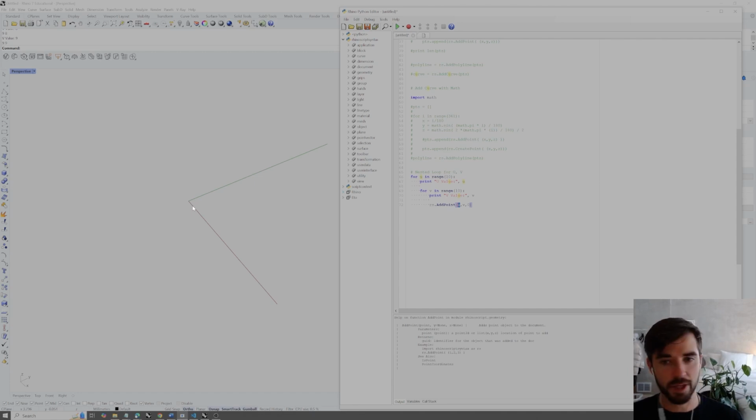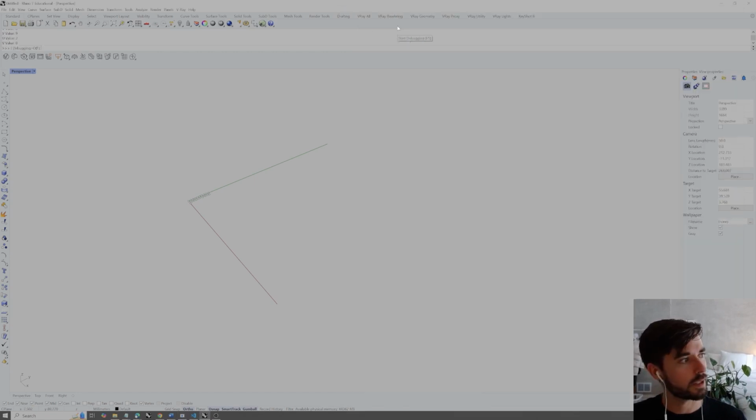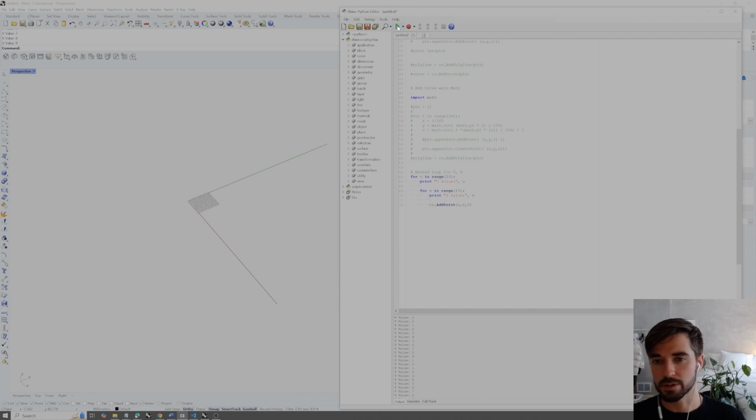Then it will step on the x one time, draw out on the y, step one more, draw out on the y. So if I hit play, we'll see these vertical rows, or vertical columns, I suppose, whatever you want to call them, being drawn out in our Rhino space. So I'll hit play to debug this, and we see those exactly as I said, just drawn out vertically.